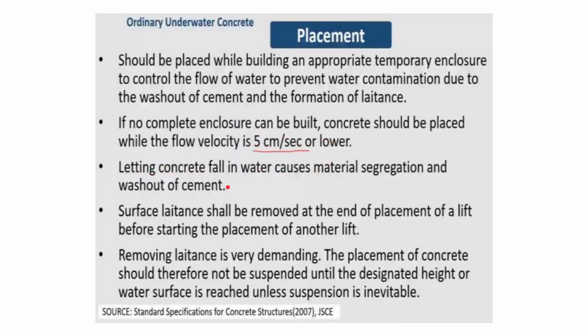So letting concrete fall in water causes material segregation, okay, and washout of cement, because water will give pressure. Okay, as per Pascal's law or any law, as you can see, it will give force in all the directions. Okay, so that will lead to segregation and washout.